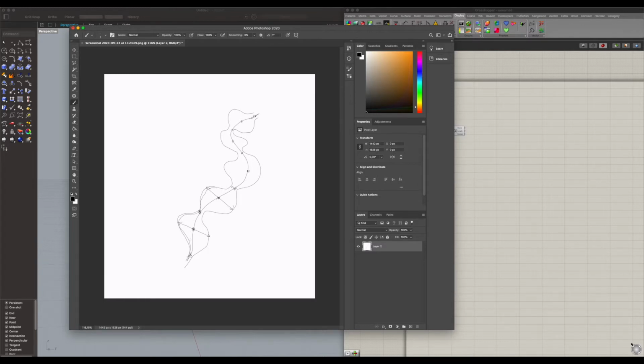to generate perpendicular planes in our curve at these given subdivision points, and every plane has an origin, which could be these points, and x, y, and z directions. So we can extract these x, y, and z directions as vectors and then use those for moving our points.